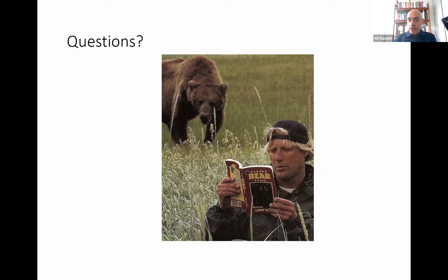And then there are some validation studies. Especially ambient vibration is the easiest one, where by measuring ambient vibration we can check the period of the dam, and that's almost the cheapest validation. Then we can compare with the FEA model, but we can do as much as you can pay. You can do very expensive active vibration studies to more carefully study the modes of vibration.